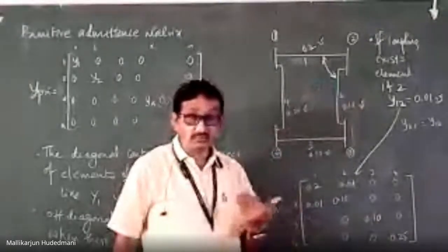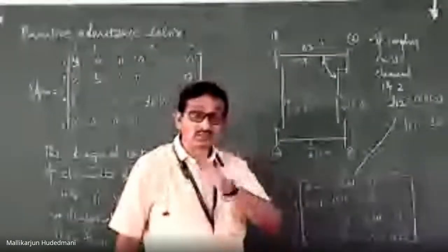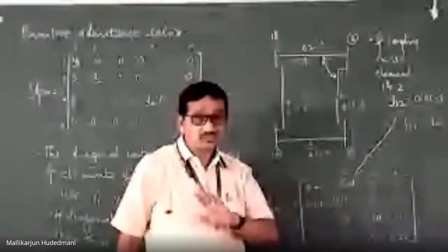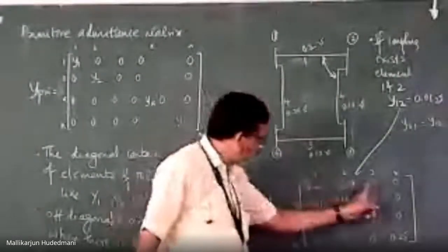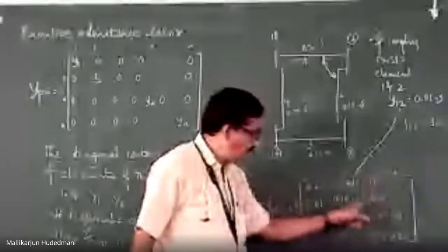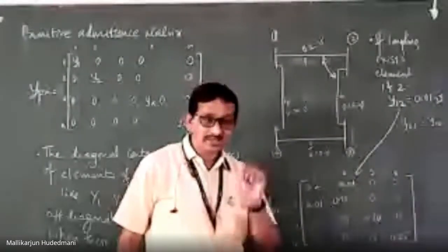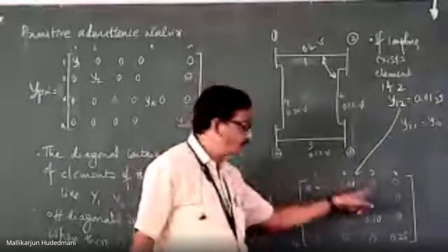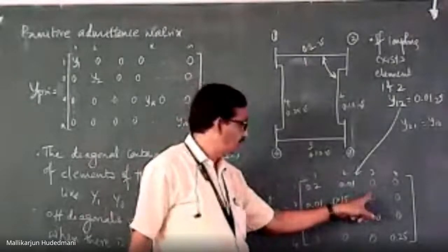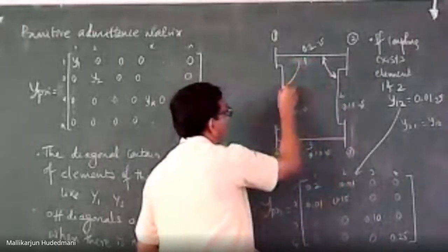There can be a number of transmission lines having mutual coupling with a number of other transmission lines. Then those many mutual couplings, those many non-zeros will be found here. It is basically zero if there is no coupling. If there exists a coupling, that coupling will represent its truthful mutual admittance in the position mentioned. Suppose this line also has coupling between 1 and 4.